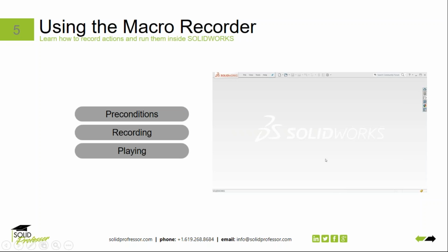All right, so this lesson is one of the most classical steps to mastering the SOLIDWORKS API. An important component of design automation in SOLIDWORKS are macros, which are small scripts written in the VBA programming language. When it comes to macros, we can record almost all actions that we can perform in the SOLIDWORKS graphical user interface.